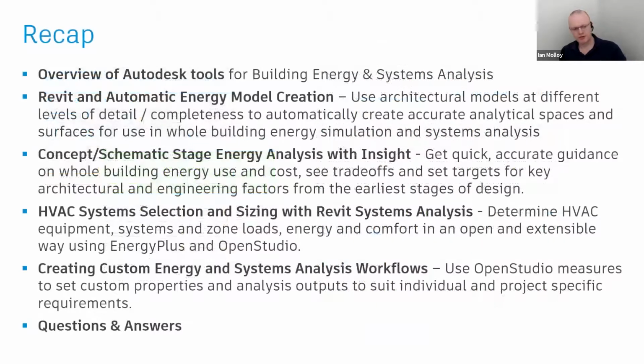Just a little recap of what we covered there of the tools, basically being Revit, Insight and systems analysis, automatic energy model creation from conceptual through to detailed, where Insight can play a big role for those early stages, discovery and targeting and trade-offs. And then more detailed energy and systems analysis using EnergyPlus and OpenStudio, with the ability to actually completely customize the way that works, not only for the analysis, but also connect it more into your BIM workflow and your BIM content. So I'm going to stop there.